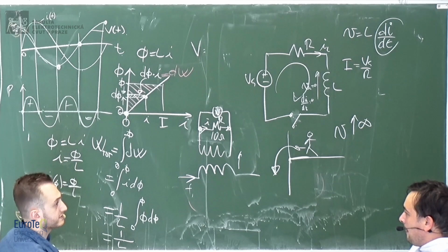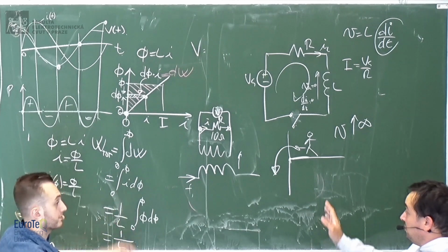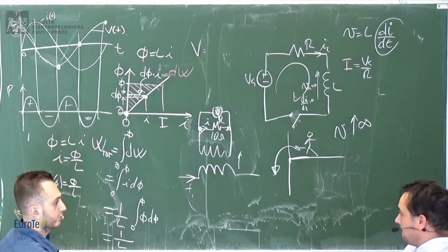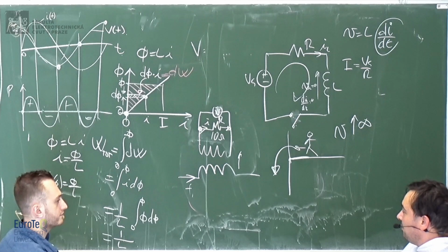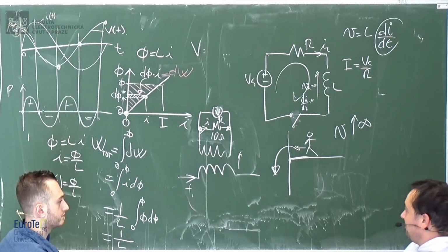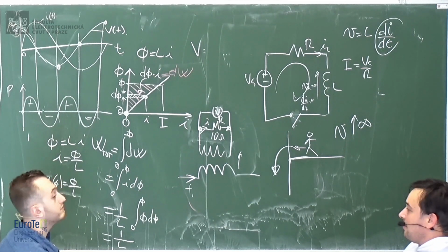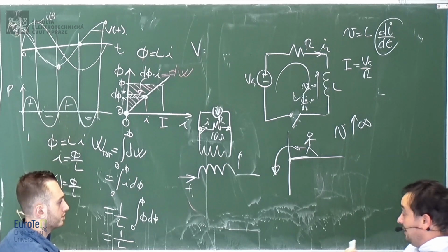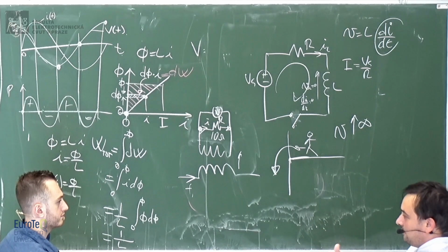So for very small currents, you might affect the circuit. This is used when you have a large current, of course, and you don't want to touch that circuit. So it's always invasive. It's always taking some amount of energy from the circuit. The advantage, as you said, is that sometimes you just go there, you clamp, and that's it.